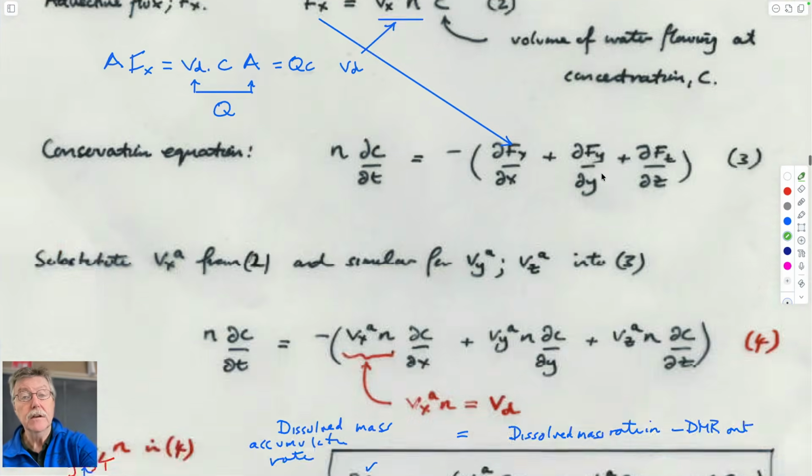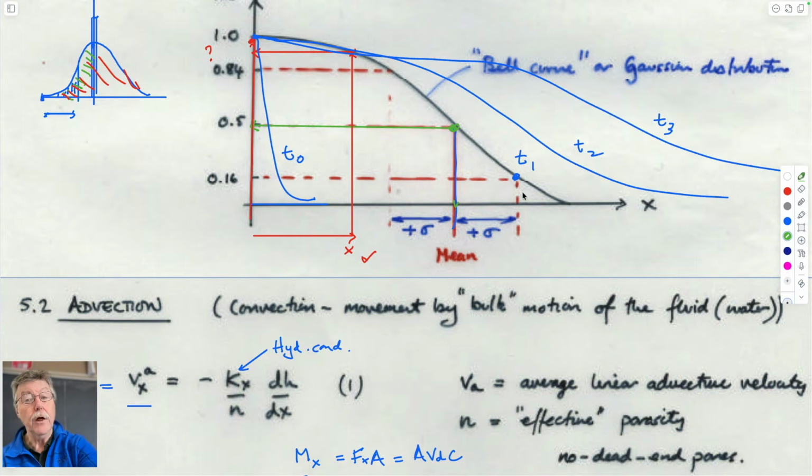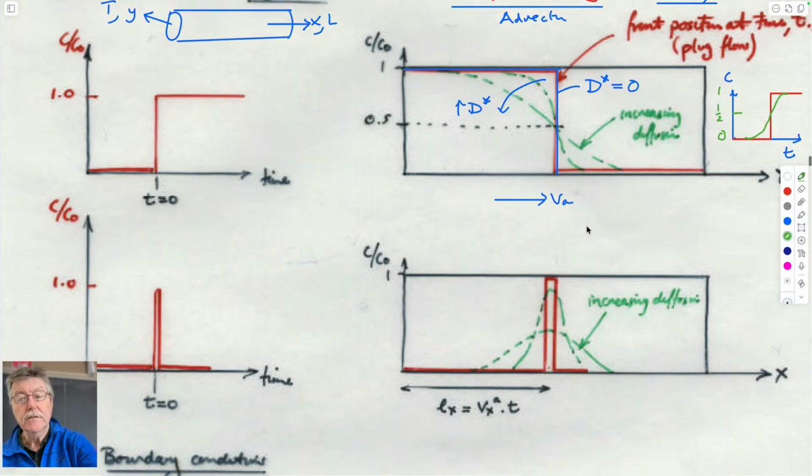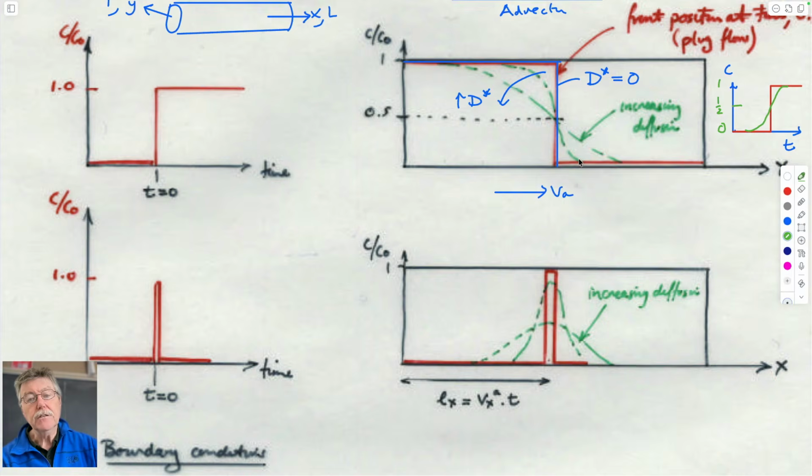Well, that can occur, of course, because we know that even if water isn't flowing, it can move downstream on its own by random walk, Brownian motion. So this is a function of the fact that the concentration gradient, and of course the concentration gradient here is infinite. This is dc and this is dx. So dc/dx goes to infinity, right? At this point here. And so that means the diffusion driving the mass transfer ahead of the front is big, but can't reach very far. But the mechanism is exactly that.